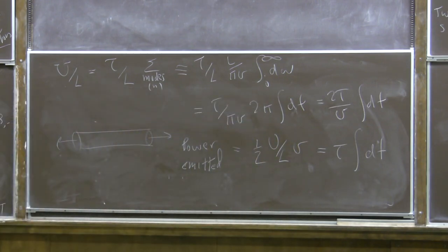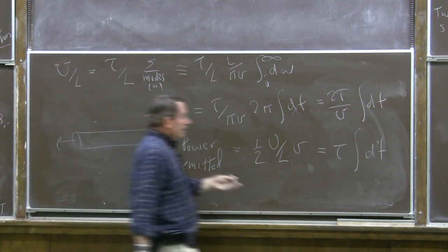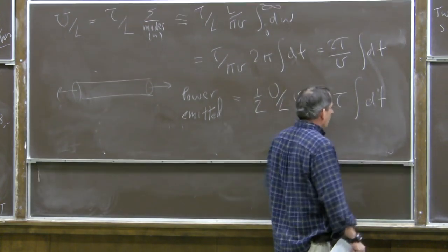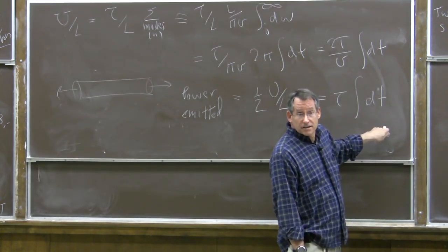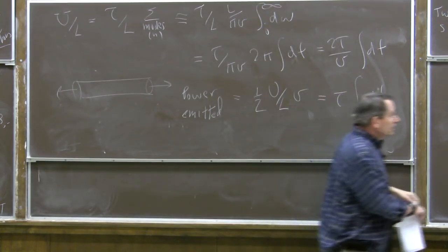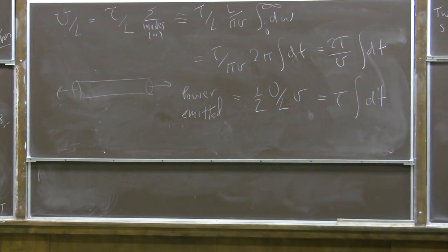Okay, but we're looking at the filtered power because we're only interested in the contribution to the dissipation in the resistance at the end coming in a certain frequency interval. So we're going to integrate f over the bandwidth to get the contribution to the signal coming from power in a certain frequency window. All right.